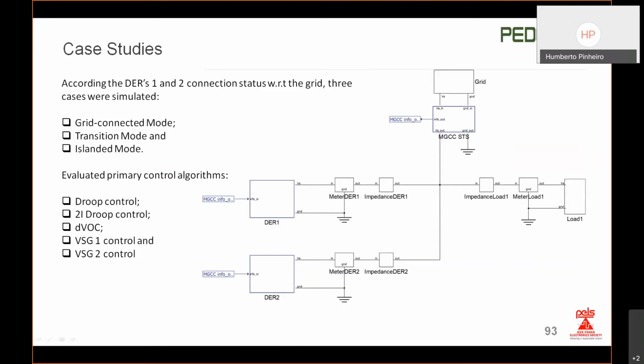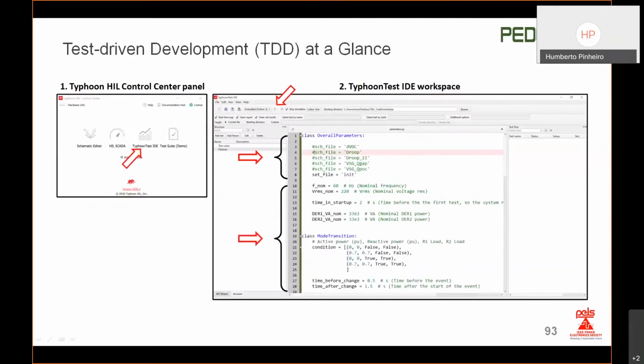We understand that this is the most critical transition, since in another transition the microgrid central controller is able to define the set points of the DERs and bring, for instance, the active power to the grid to 0 and then open the switch. So this doesn't give you any surprise, I would say. This is the reason that we focus on the unplanned island in terms of transition.